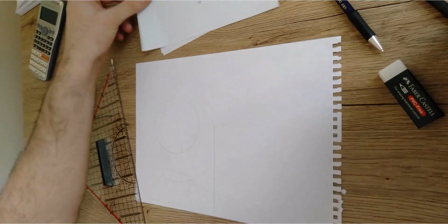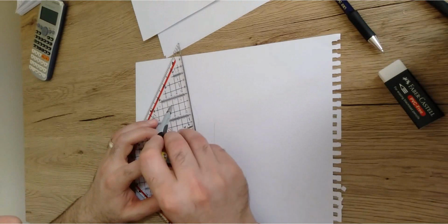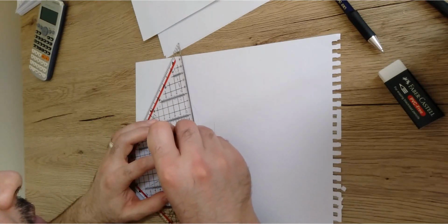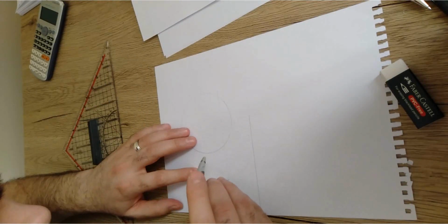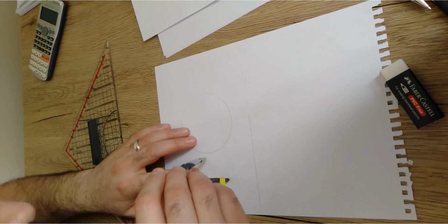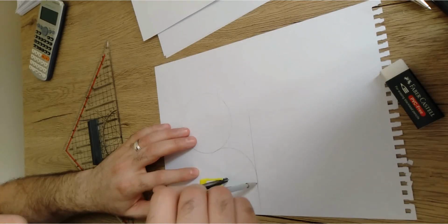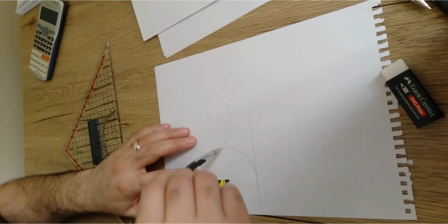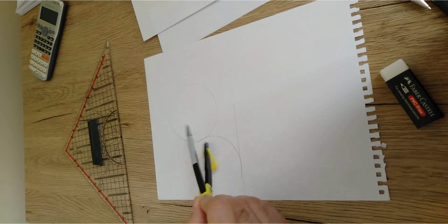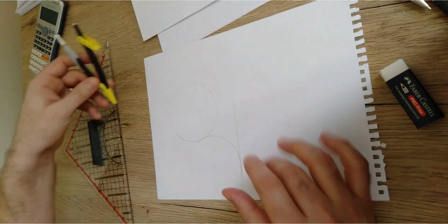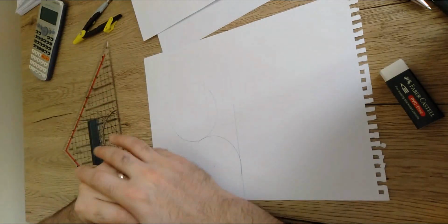Then we're gonna open the compass with the radius of the curve, which is already given by 40, to draw the curve. So from this point, I'm just gonna fix here and draw a curve. Make sure that it is already over the center point. It's gonna be tangent to the first circle and as well tangent to the line. As you can see, there is some intersection, but it is just acceptable, especially on this side, and on the other side. But anyway, we can manage this with the finishing that we're gonna do once we finish this drawing.